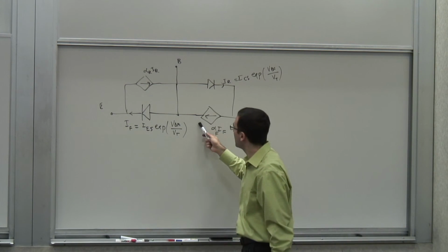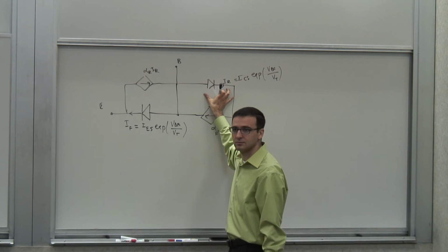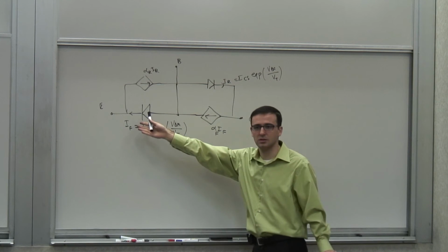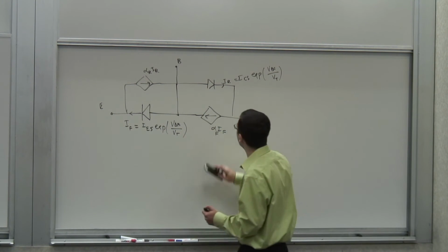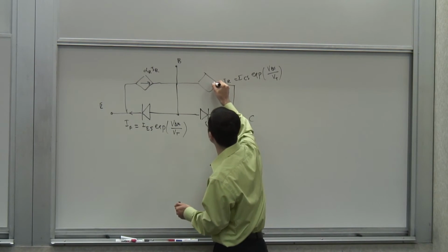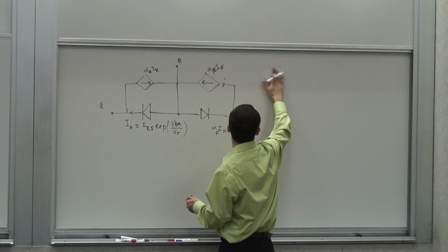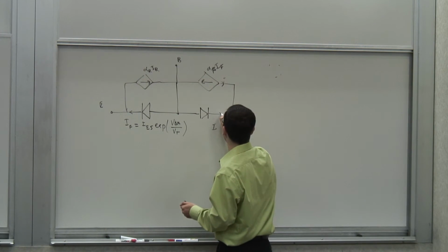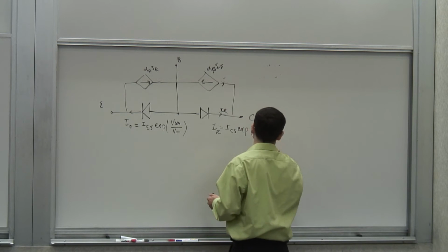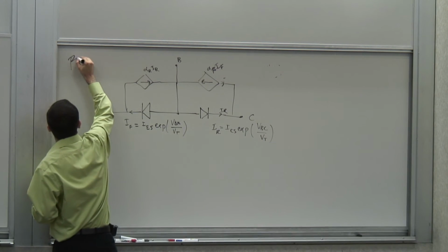And this kind of subsumes that, because think about it, if this is reverse biased, this diode is off, therefore this current is 0, so these two disappear, and this is what you're left with. In fact, you often redraw it slightly differently, so you put the two diodes in one place, and the two dependent current sources, alpha F IF, and this is going to be alpha R IR, which is ICS e^(VBC/VT). Okay? This is called the Ebers-Moll model after the two guys who came up with it.